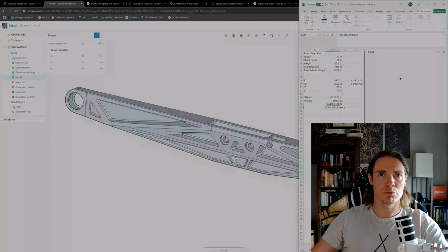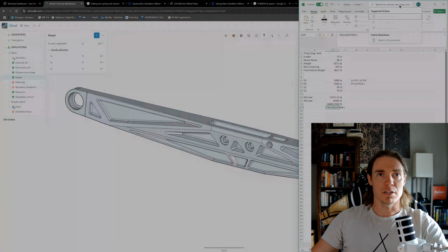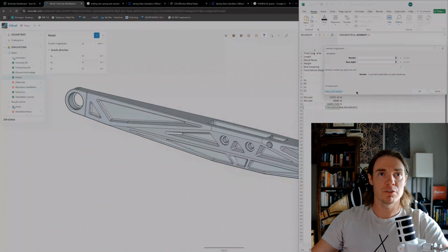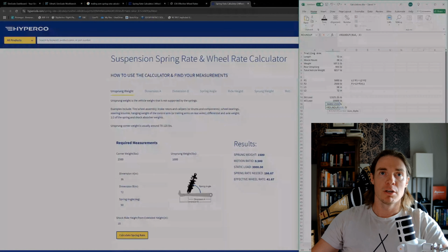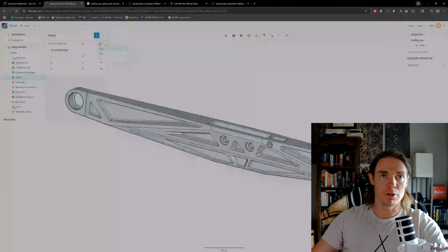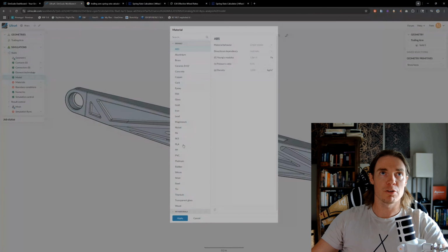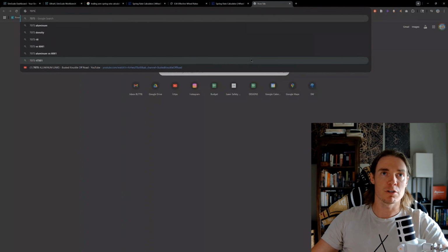And most FEA tools like this have a similar user interface, so it's pretty easy to get started with something like this. And the units in here are defaulted to metric, and I like to keep it that way because there's a lot of material properties that are quoted metric, and it's easy to convert them from pound force to newtons. So there's another resource called MatWeb, and it's a database of every material under the sun.